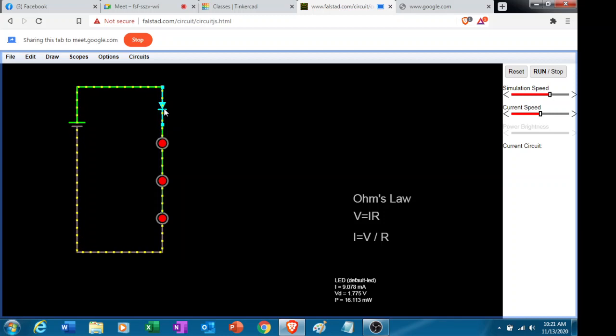So I adjusted the voltage because the typical, average current for an LED is around 10 milliamps, and if you read the current now, it's 9 milliamps. Can you see it? So therefore, we're operating in normal current. It's not over current.